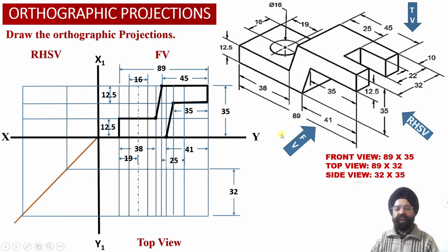As the observer will be viewing the solid from this orientation, the true shape projections corresponding to this surface, which will be corresponding to element 1, element 2 and element 3, will be obtained onto the vertical plane, because this surface happens to be parallel to the vertical plane.